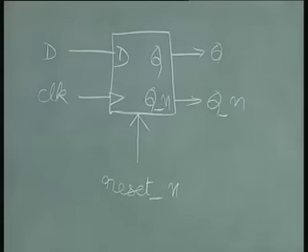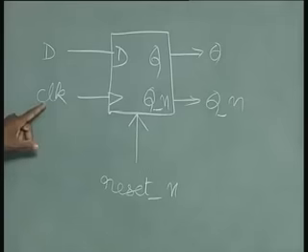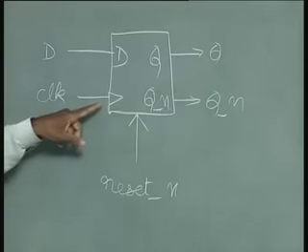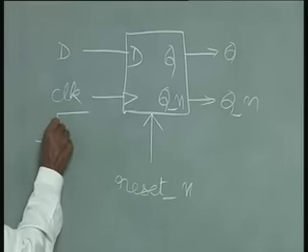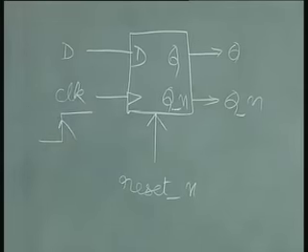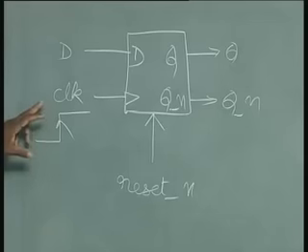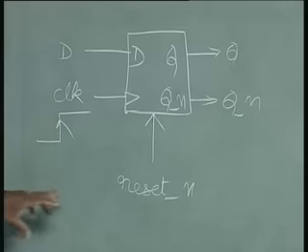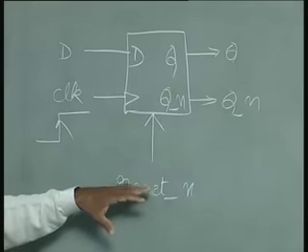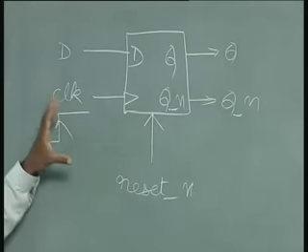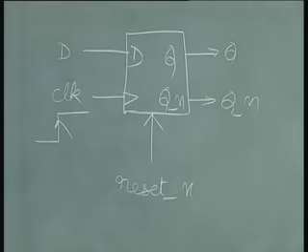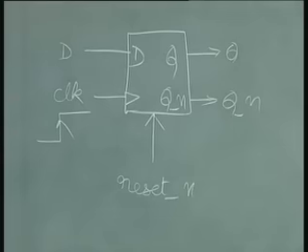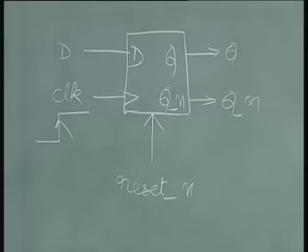And another thing that we have seen here is a clock input. You have already seen that it signifies a positive edge clock. And once again, this positive edge of clock and asynchronous reset active low, these are very popular among designers, especially in United States, and we adopt this throughout our course as such. And now it's very easy to code this.